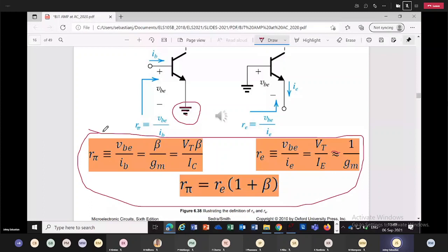Primary voltage of a transformer to the secondary voltage: primary voltage divided by turns ratio. From transformer secondary voltage to peak rectified voltage Vm, that is RMS to peak conversion: V secondary times square root of 2 minus diode voltage.